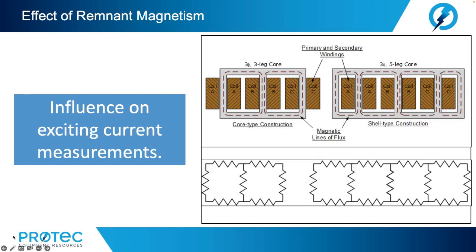The assessment is performed based on a typical pattern of a 3-limb or 5-limb transformer or based on reference measurements if they are available. The magnitude of the magnetization current depends on the length of the magnetized path. This is virtually identical for the windings on the outer limbs, but lower for the windings on the middle limb. If there is, for example, residual magnetism on the middle limb, this can easily lead to incorrect interpretation and a reliable diagnosis becomes impossible.